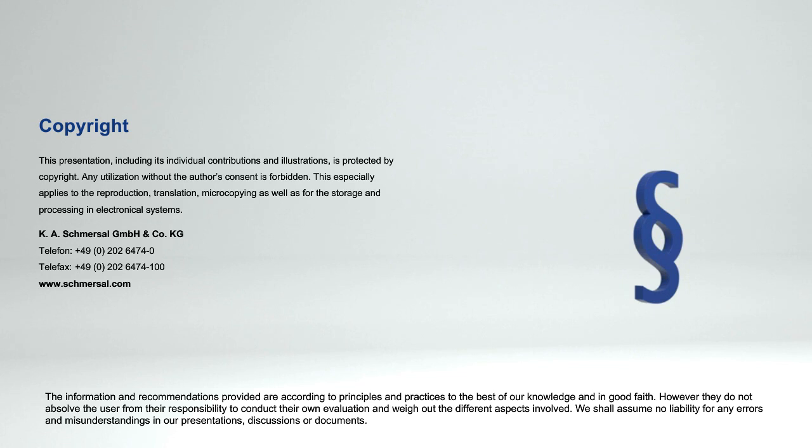Well, how do we get that? With electromechanical switches, we have some additional calculations that go in there. We could have a controller that's purely electronic. There are no electromechanical parts, so the manufacturer of that controller could supply a PFA or a PFH, which relates to a performance level or SIL level potential.